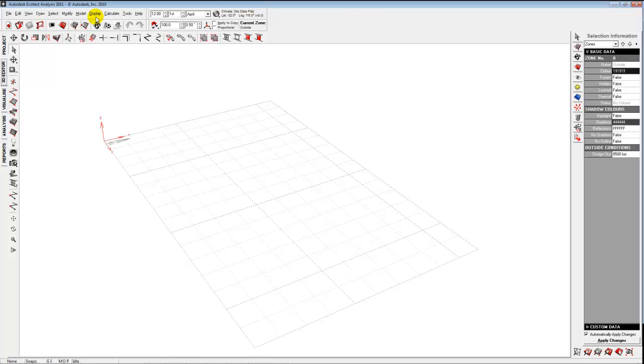A lot of things we do as we're modeling architecturally don't necessarily have to be complete and totally accurate, in that they're not always closed surfaces or they're not always contained volumes. When we bring those in and start trying to do the analysis, like a thermal analysis, that'll be very important, because if there's any holes in the surface, heat will leak in or leak out of the building. So we need to close some of those things. But let's start with creating a very basic model, and then we'll take a look at some problem cases and think about how you might fix those.